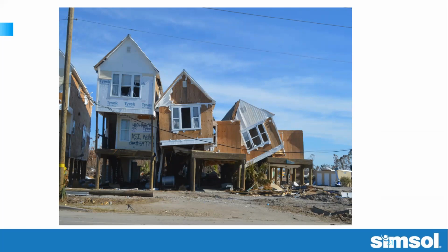Another thing that I'm also noticing, this is an elevated structure. No siding, so the water would go underneath it and free flowing. Yes. Now, I wouldn't necessarily say free flowing. Some of these had small enclosures with breakaway systems underneath. So if you put any kind of vertical wall below that first elevated floor, those are mandated to be breakaway systems, so you don't create an impediment in the floodway.